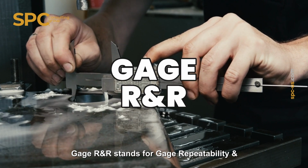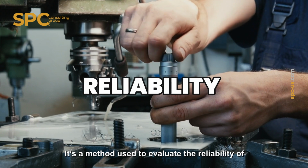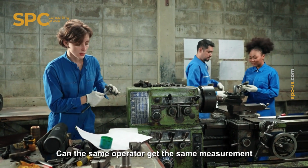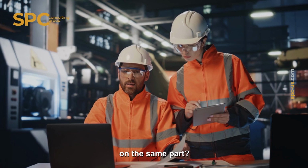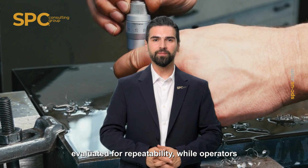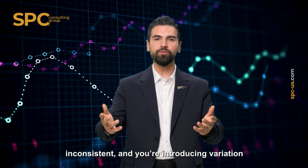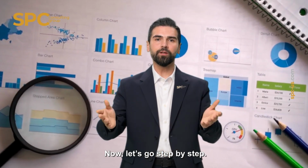Gage R&R stands for Gauge Repeatability and Reproducibility. It's a method used to evaluate the reliability of a measurement system by checking two key aspects. Repeatability. Can the same operator get the same measurement every time? Reproducibility. Can different operators get the same measurement on the same part? In this type of study, measurement equipment is evaluated for repeatability, while operators are evaluated for reproducibility. If your Gage R&R is bad, your measurements are inconsistent, and you're introducing variation into your process, which leads to quality issues and scrap. Now, let's go step by step.